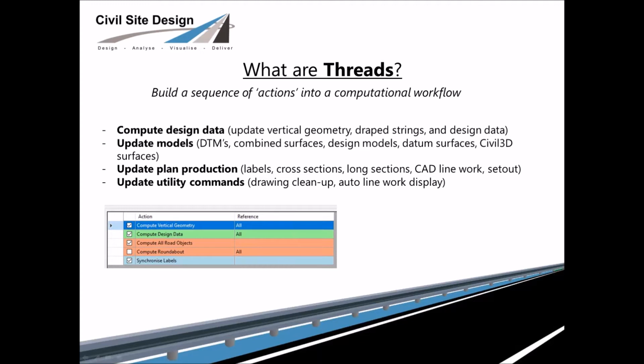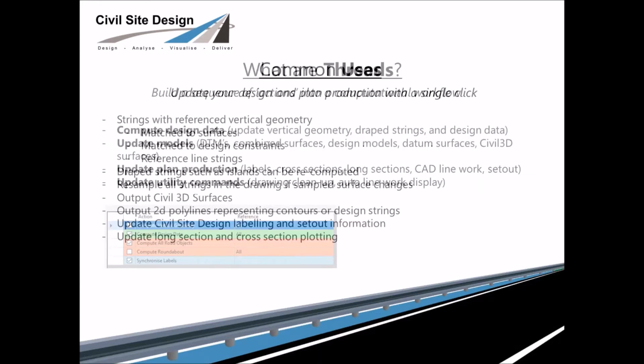Today I'll be demonstrating a couple of examples of where threads will benefit you, but there are many benefits, and even here in the office we're discovering more. If you work on larger projects, then this will be great for you because you can turn off a lot of the auto rebuilds in the software and rely on threads to update your design when you want.